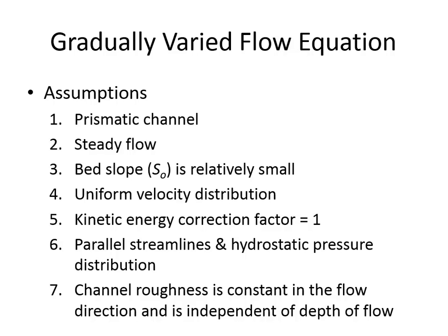We're going to assume that the bed slope is relatively small. The reason we're assuming that is because we want to be able to say that the flow depth and the vertical depth are approximately equal. We've looked at this a couple of times: if we had a super steep channel, there would be a difference between this depth, y, and the vertical depth.